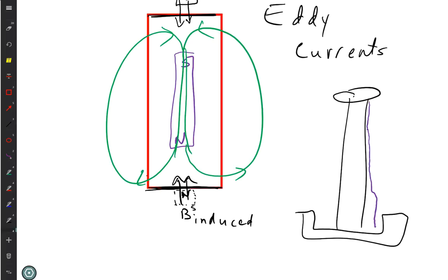Normally we get bad economy for city driving because you hit the accelerator, you use energy. You hit the brake, and you dump energy. But with those, you hit the accelerator, energy goes into kinetic energy, you hit the brake, and it goes back to the battery. When you're driving down the freeway, of course, where's the energy going?